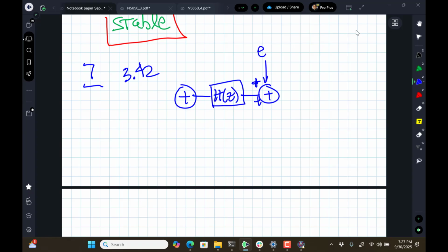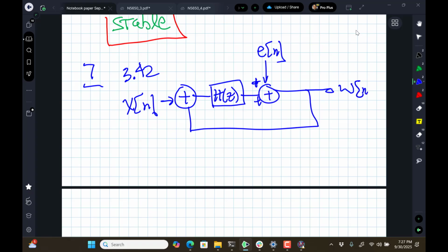So it's called superposition in a linear feedback, or in block diagrams, I mean. So what you have to do when you have a feedback system and you know linearity applies, if you want to find W of z, so what you want to be able to do is switch this to the z domain, because then it's just algebraic.